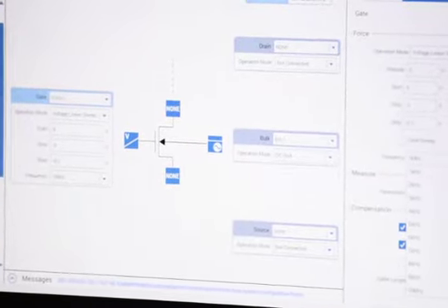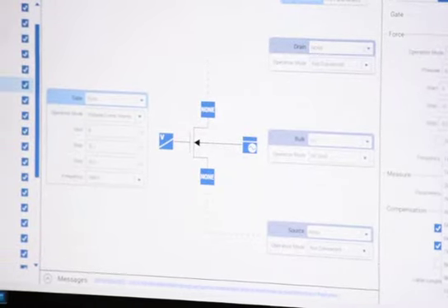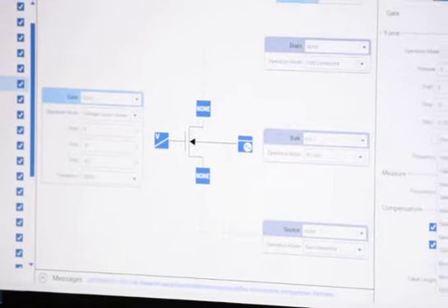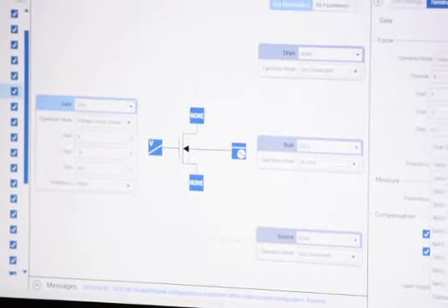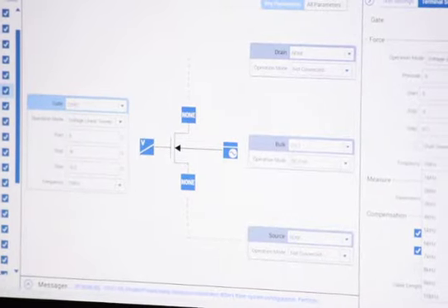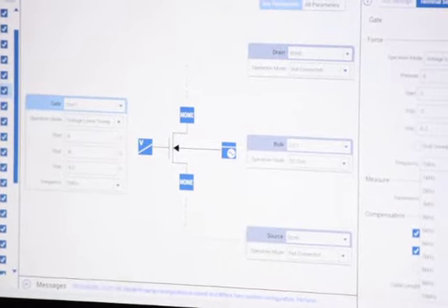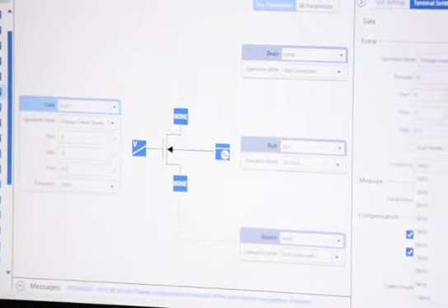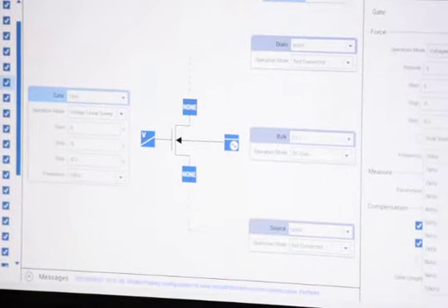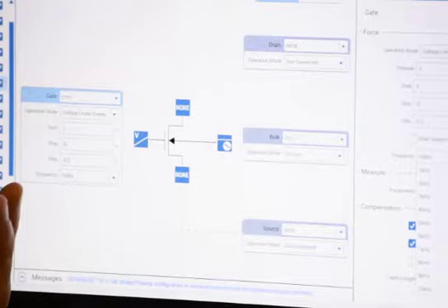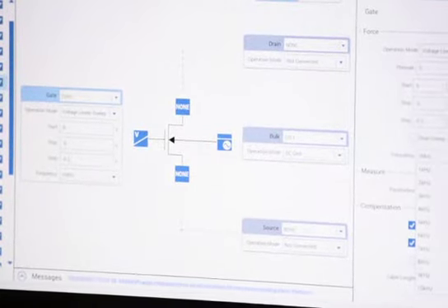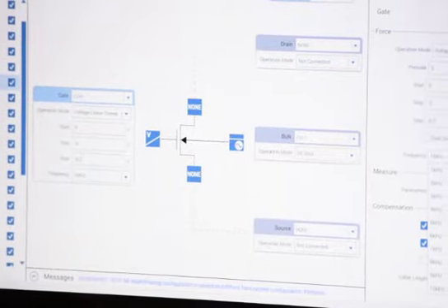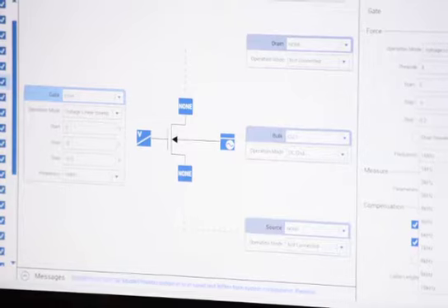I can't tell you that, but I can tell you that if you publish a paper on an uncalibrated system, somebody's going to question that. So you don't want that. That's a bad thing. Is there a way to know if it is not calibrated in the system? Send it in. Calibration is not calibration like you're thinking. When I say calibration, it's more validation than it is calibration. When you send an instrument in for calibration, they validate: is it within calibration? And if it is, they don't touch it. If it's within the tolerances, they just ship it back to you. If it's not, now it's calibration.